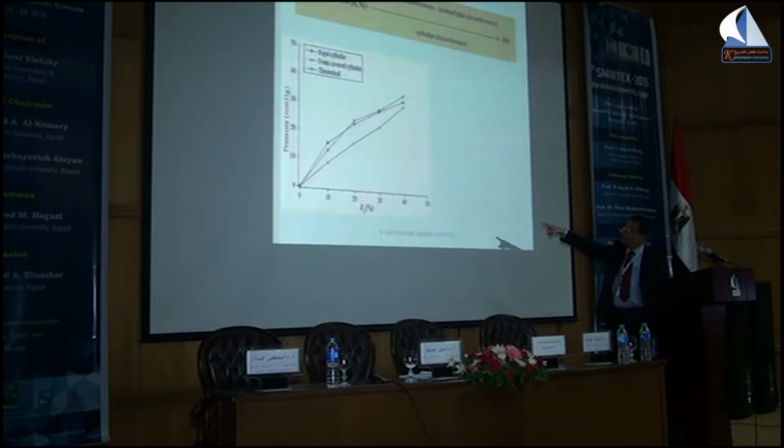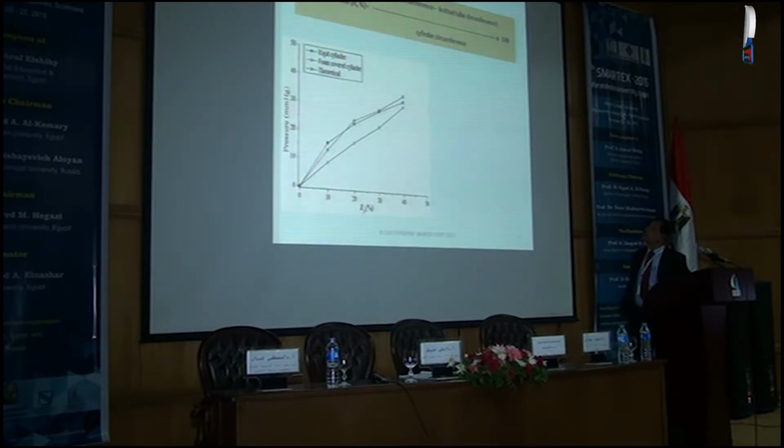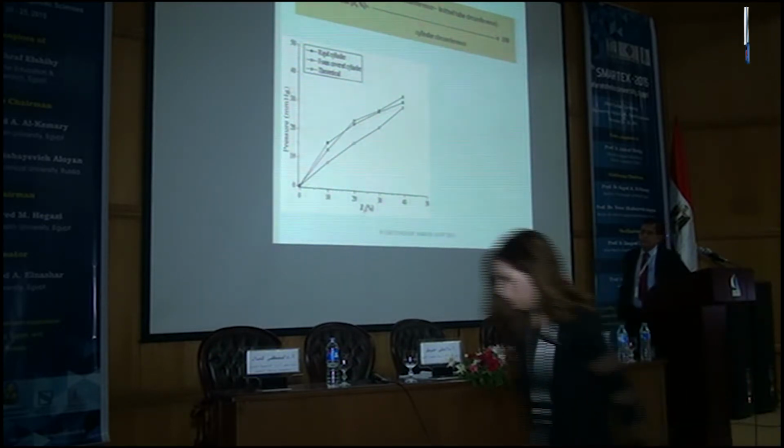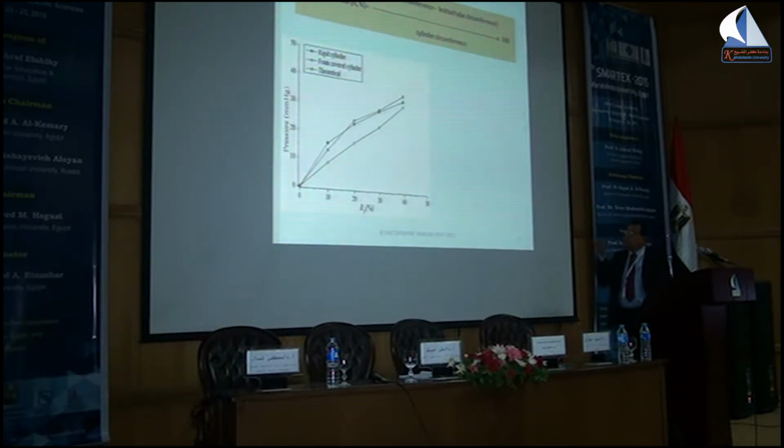The reduction factor definition is given on the top. It is the cylinder circumference minus the knitted tube circumference, divided by the cylinder circumference, multiplied by 100. This is the proportional decrease in the size of the knitted tube that we are going to put on the cylinder.